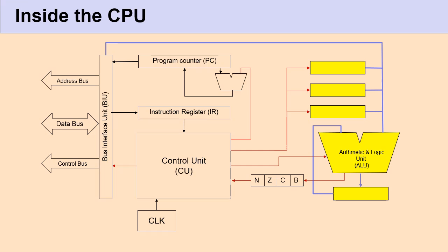It provides one input, and when the operation is completed, it stores the output also. So you can look at this like a cycle. It has the input and then becomes the output. Again, for the next instruction, it can become the input and again the output. Because of this, it's called the accumulator, because it accumulates the ALU outputs.